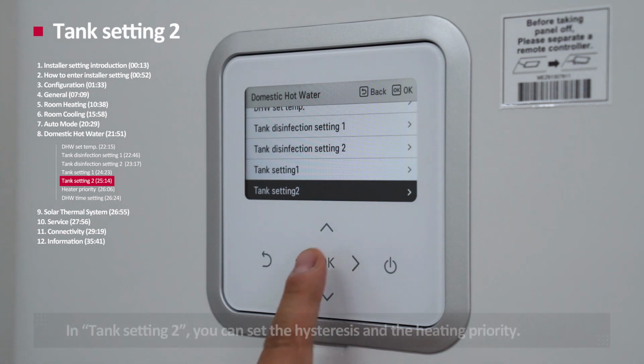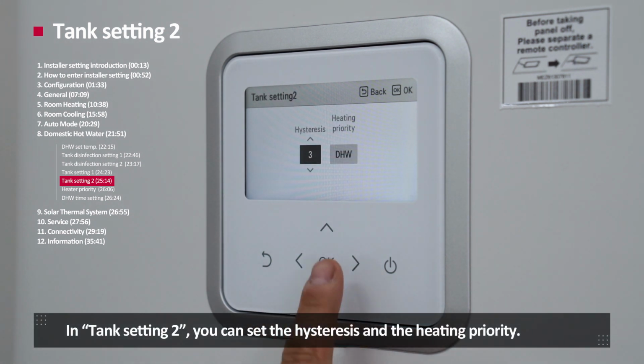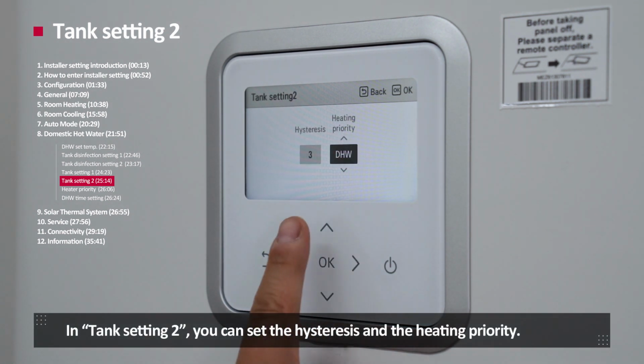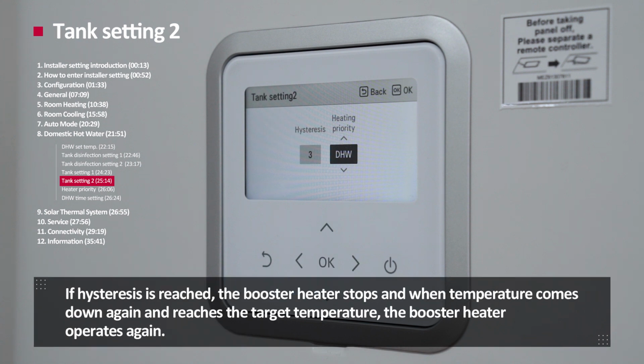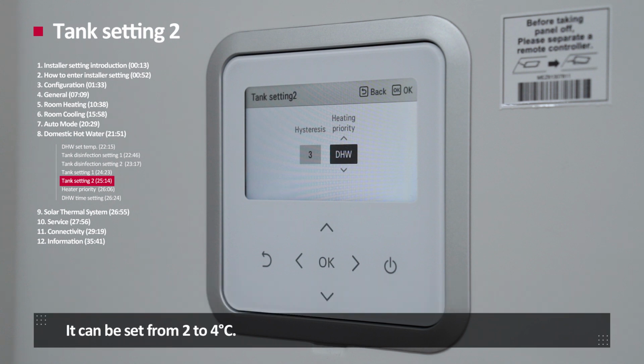Tank setting 2. In tank setting 2, you can set the hysteresis and the heating priority. Hysteresis is a marginal temperature to prevent frequent turn on and off after it reaches the target temperature. If hysteresis is reached, the booster heater stops, and when temperature comes down again and reaches the target temperature, the booster heater operates again. It can be from 2 to 4 degrees Celsius.